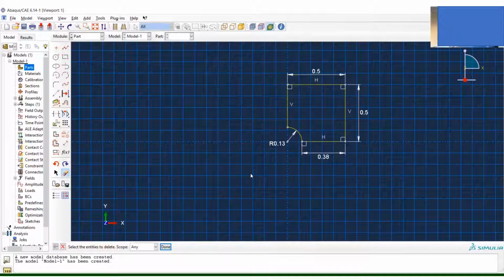Done. Okay, so this is deleted. You should know that we cannot over constrain. This is the length. Why is it a problem? Because here is 0.5, and here is 0.125, and then you define this one. We know that from the perspective of a mechanical engineer, on this length, if we define this one, that means it is over constrained. So we are okay now.